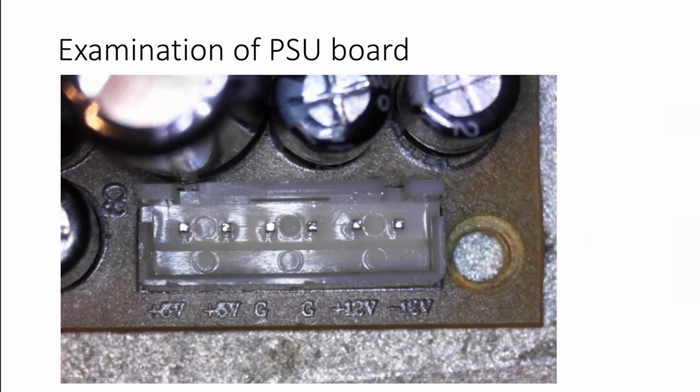As I say, one of the ground pins has been taken away to provide that earth, to connect the mains earth to the circuit earth to stop stray voltages getting onto the BNC connectors. But I'm going to assume that this thing's designed with 2 ground pins there anyway. So I can put the mains back onto it and just put the voltmeter onto these pins and see what I'm getting.